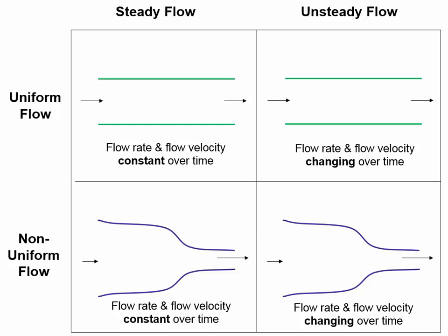When a firefighter starts opening up the valve and water is gradually increasing in velocity, then at this location in the center where the fluid is being accelerated, you'd have both unsteady and non-uniform flow, which means there's both a local and a convective acceleration at the same time.